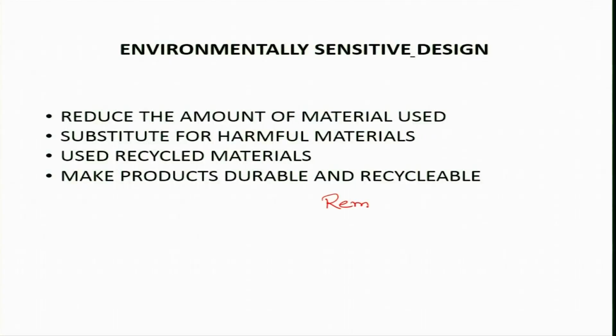In that context, remanufacturing is a very important technique which is employed especially for large equipment just like earth movers, etc. In the earth mover, we are finding that the frames, etc., which are used never wear and tear because they are non-moving parts. Whereas electronic components and other movable components get worn. They have a life of 5 years, 10 years, 20 years, different components. So if we use the concept of remanufacturing after the life is over of these components, we replace only those components which are small in number, small in size, whereas the frame, etc., we can use as it is.